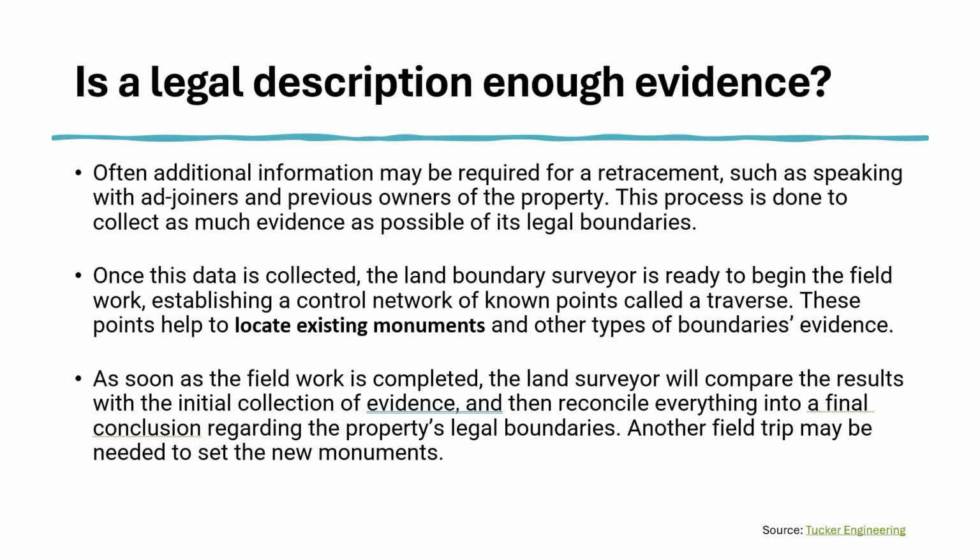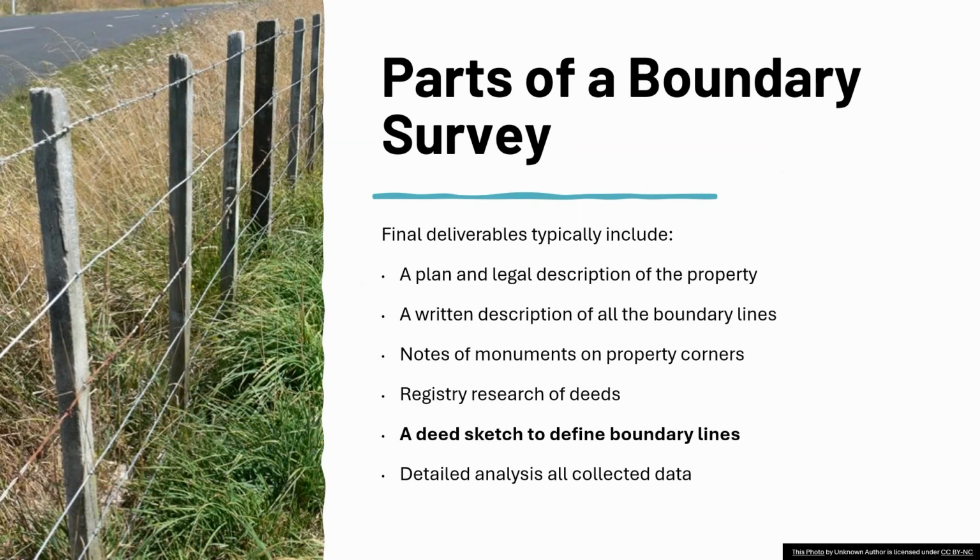All right, so let's get into the parts of a boundary survey: what your final deliverables are typically going to look like at the end of a boundary survey. You're going to have a plan and legal description of your property. You're going to have written descriptions of all your boundary lines. You're going to have notes of monuments on your property corners. The registry research of deeds, so everything you collected from the courthouse, the legal documentation on it.